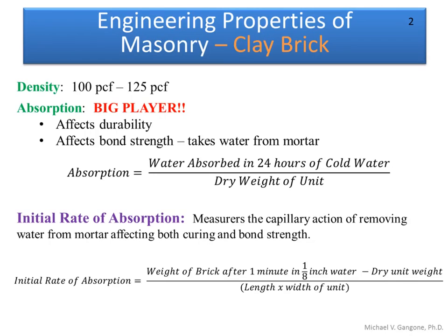All right, density. When we're talking about first clay bricks, you can see the density here. Absorption is a big player when it comes to clay brick. Clay is a very absorbent material. It wants to take in a lot of water, so it's something very important to keep in mind. Like I said, it does affect the durability, and it affects the bond strength. In particular, when we're talking about absorption,